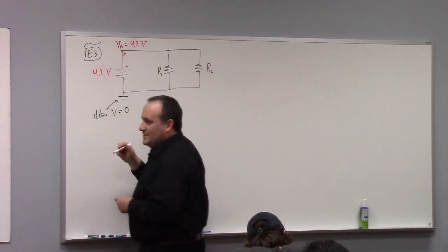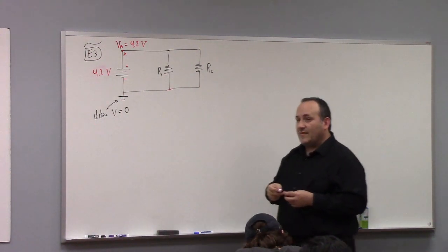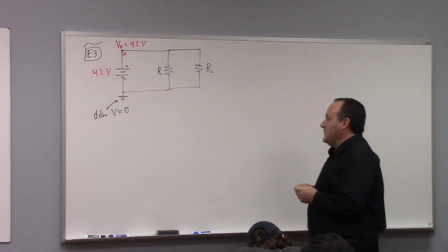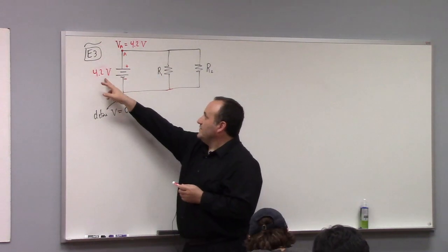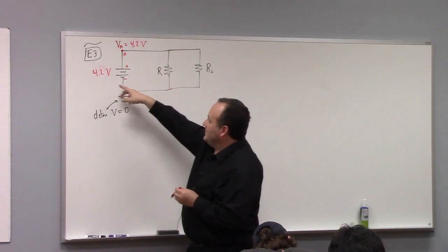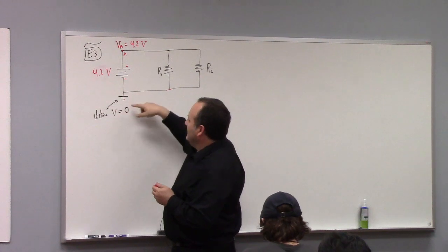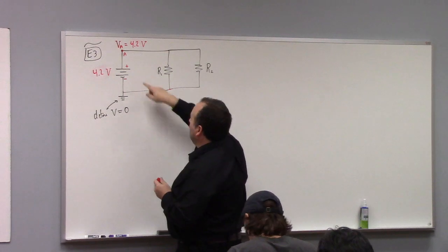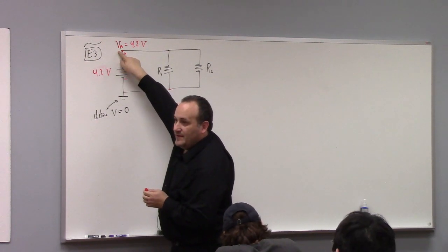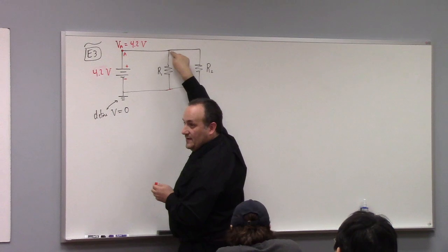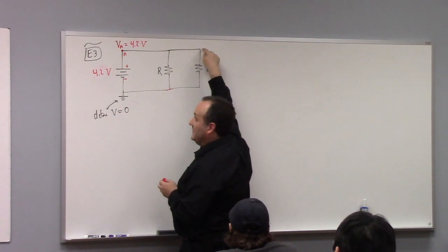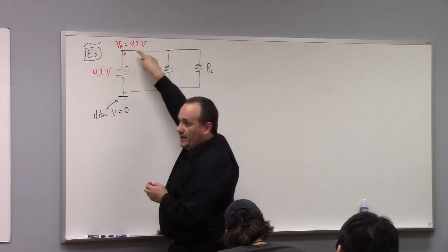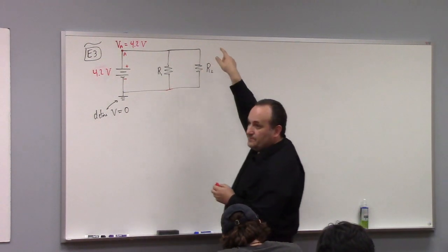This is the voltage of a typical lithium-ion cell. So if the voltage is 0 here, 4.2 up here, right? And if it's 4.2 volts here, it's also 4.2 volts here. It's also 4.2 volts here, because this is all at the same node. So when it's physically connected with a wire with no circuit elements between it, same voltage.